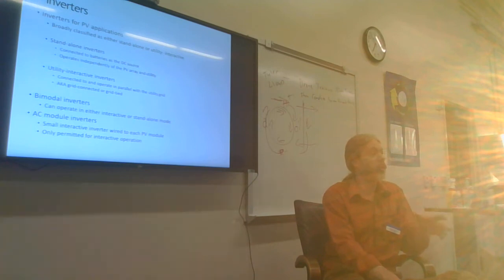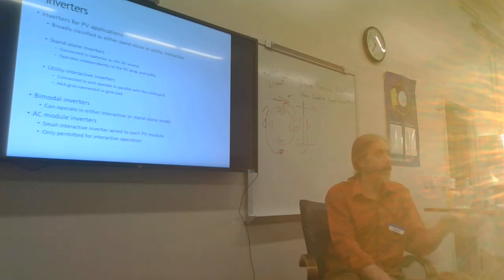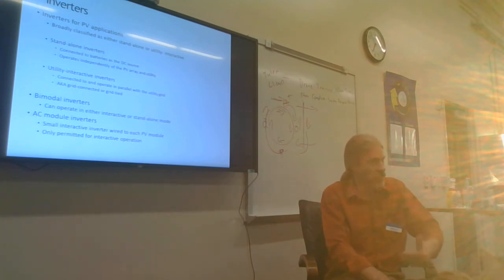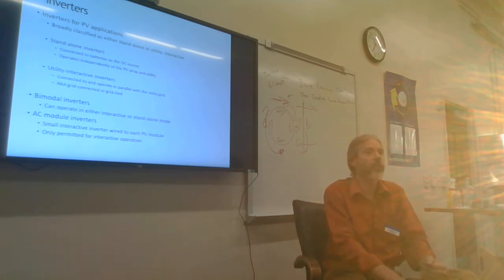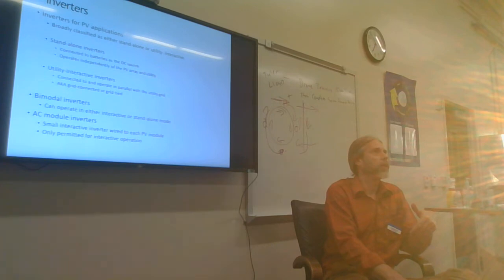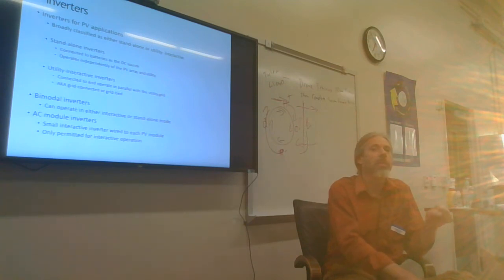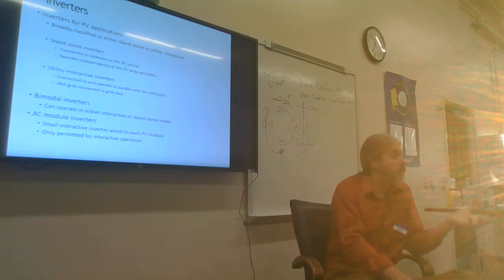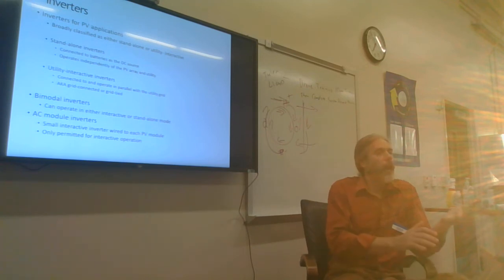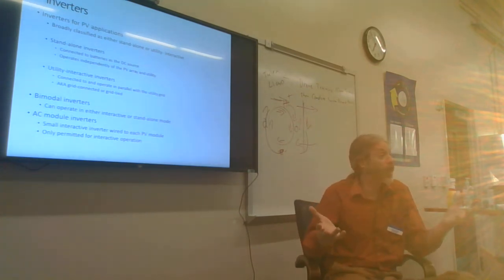And their air conditioning load is so large that it has a tremendous drain on their batteries and on their PV system. So they install an additional array with microinverters on it that is connected to their existing system. It will only function and come on if the system is using more power than it needs. Does that make sense? So I hate that concept. I think you're just wasting a whole lot of energy to do it.